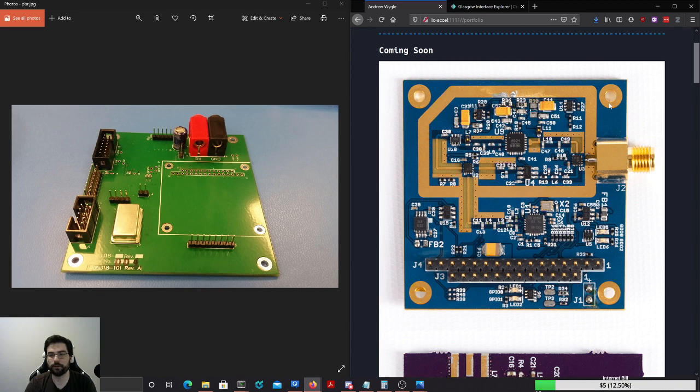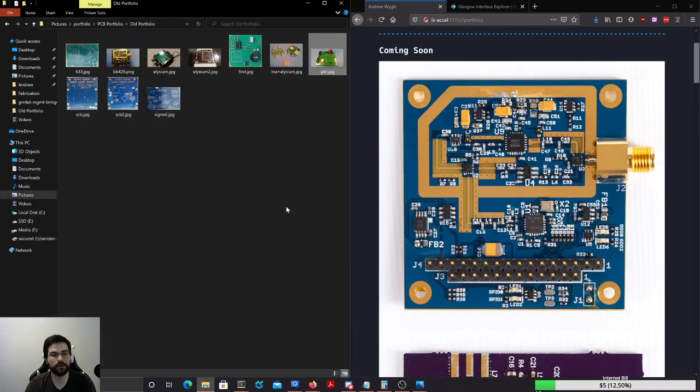But we had this board, but we had nothing to talk to it. So this board communicates over just a regular SPI interface, and we had nothing with which to communicate with it. So we hacked this thing together in like a day and a half. It's just a carrier card for this radio, and it has an MSP430 on the back. That's it. It was an incredible rush job. It's on the cheapest, crappiest plastic PCB you could possibly buy. Yeah, this thing was awful, but it served its purpose. We needed something that we could test with, and we got it.